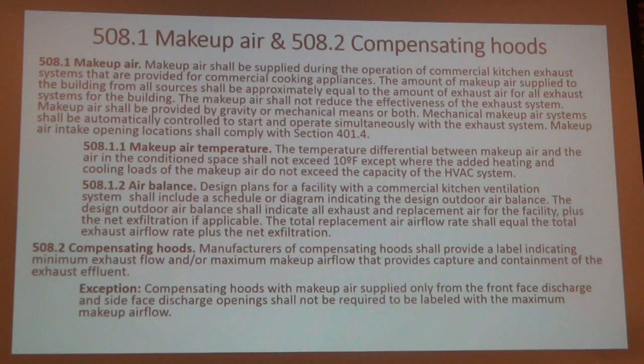Now, the commentary says that if the makeup air is right next to the hood, they feel it doesn't have to be tempered because it's going to be sucked right into the hood. That's their comment. You can take the commentary with a grain of salt or not. I always thought for the longest time it was heating only, but it's technically for heating and cooling.